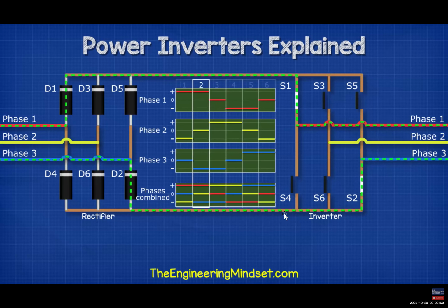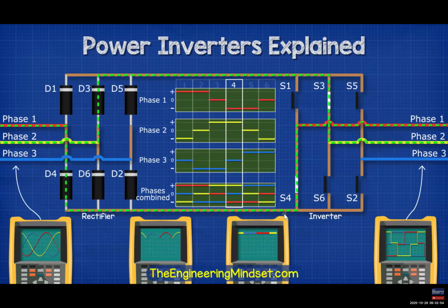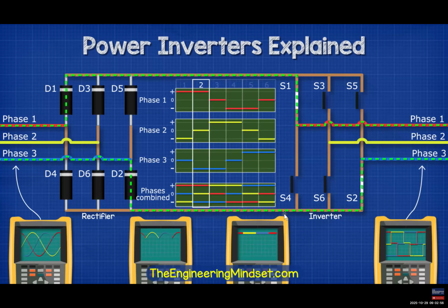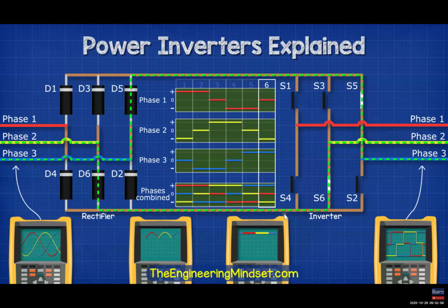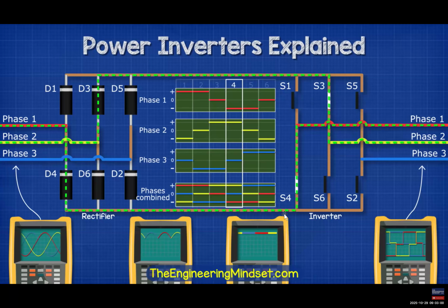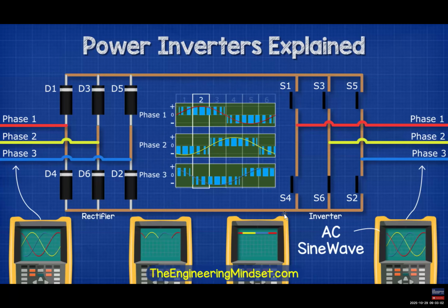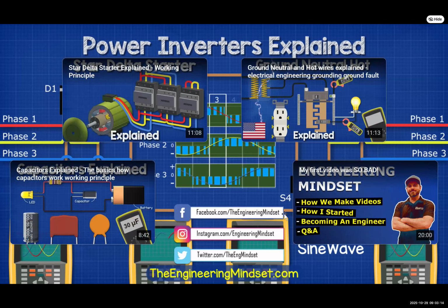If we check this with an oscilloscope, we now have a wave pattern that looks something like AC, except it's still a little bit square. This will work fine for some applications, but not all. So again, we need to use pulse width modulation to create the sine wave. So we're going to use a controller to rapidly open and close the switches to vary the output frequency and voltage, and that way we get our three-phase AC supply.